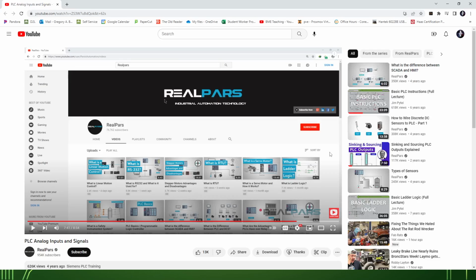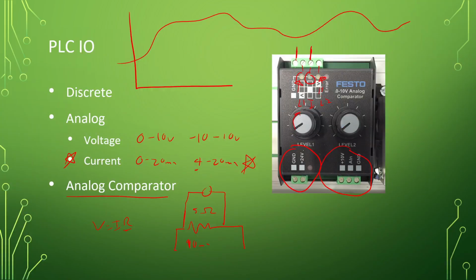There's so many weird tweaks to thermocouples like that. And you would think it's just analog measurement, right? All right. So again, remember I talked about being pseudo smart. Yeah, okay, you could have an analog sensor that takes a thermocouple input and still outputs a 0 to 10 volt or 4 to 20 milliamp signal. A little bit of give and take going on there.